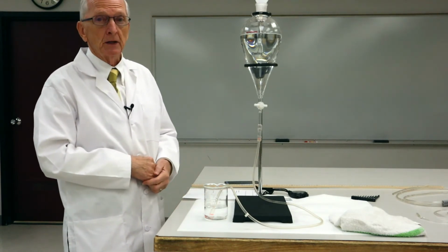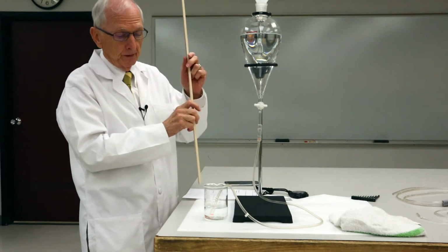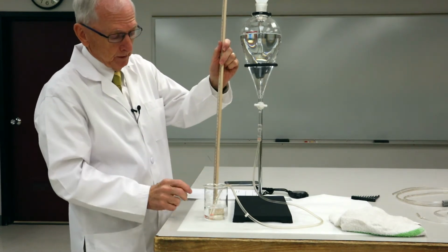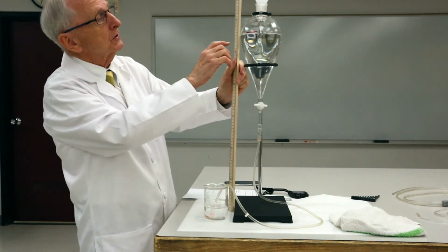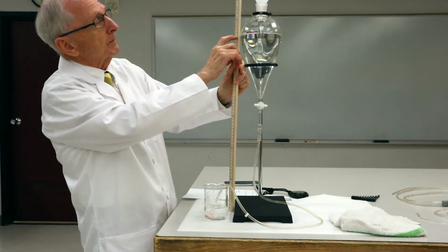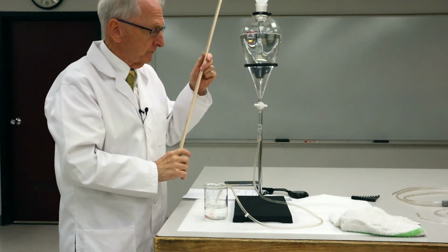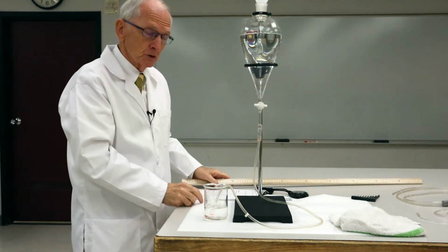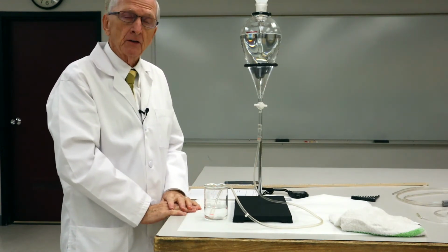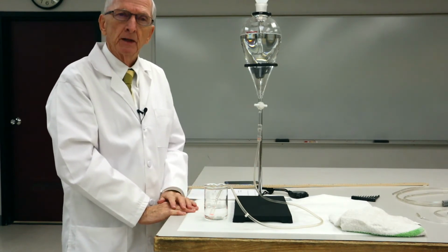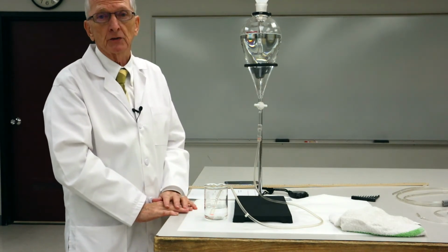And then to find delta P, you have an equation that relates the pressure to the height of the water column. And that height is the difference between where it came out of the tube, which is pretty much this tabletop, to the height of the water at the top. And I measure that as 55.5 centimeters. Please use that to find delta P. And then using equation 3.7, calculate the fluid resistance for this tube in clinical units. The clinical units would be liters, seconds, and millimeters of mercury.